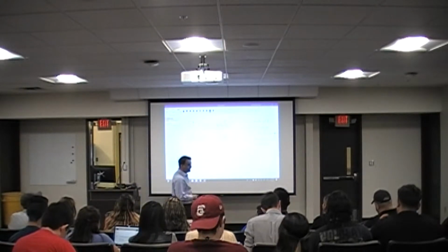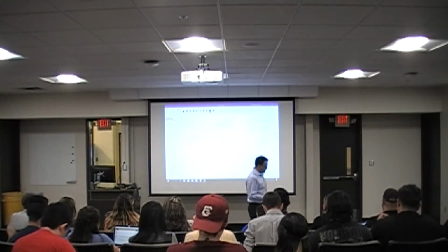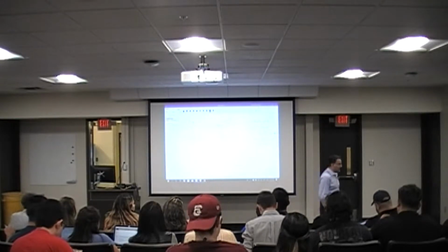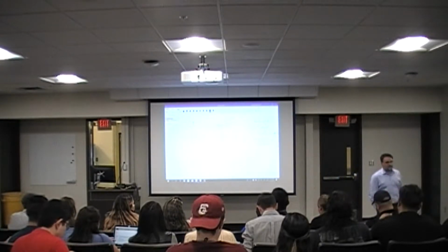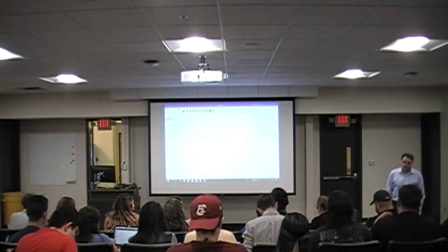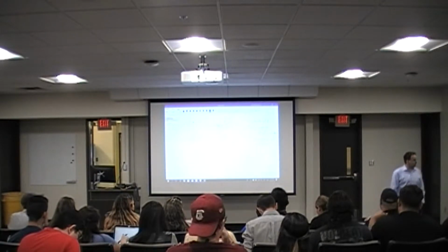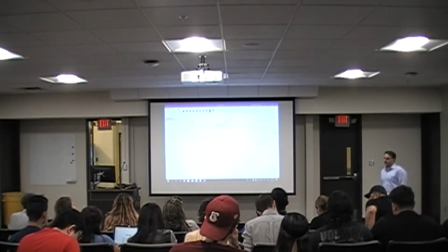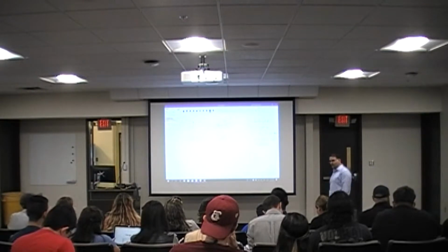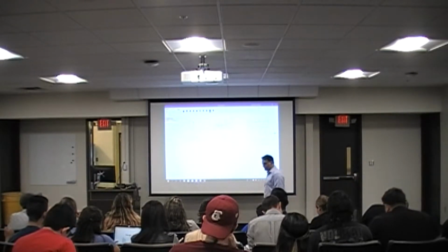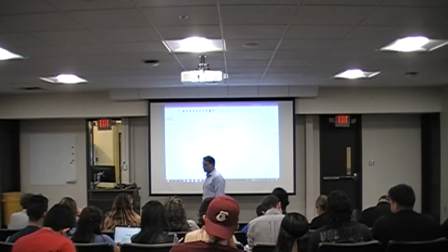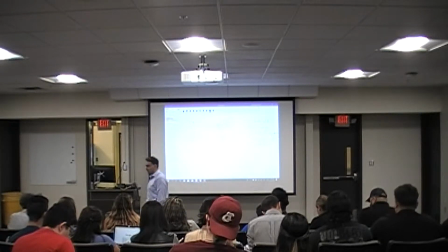Today we're going to talk about the direct shear test, and that's a test that we run in the lab to be able to get the C value and phi value, if you will, to be able to properly characterize the Mohr-Coulomb failure envelope. And in our next lecture we'll talk about the triaxial test. Specifically we'll talk about the triaxial shear test to be able to get the C and phi value.